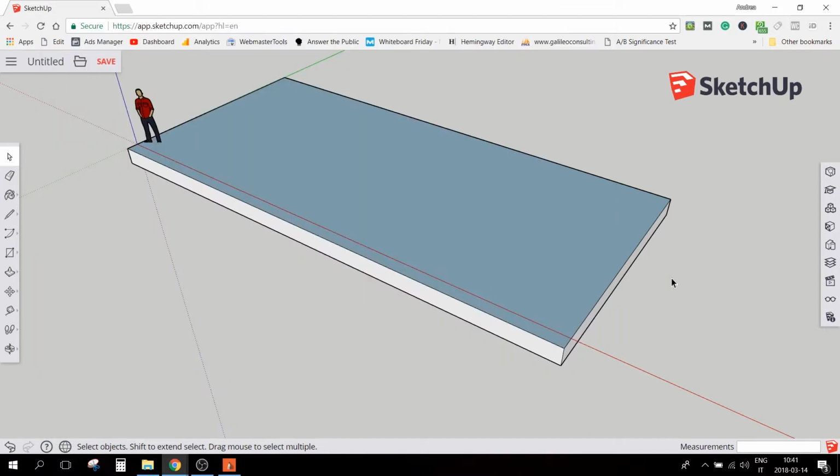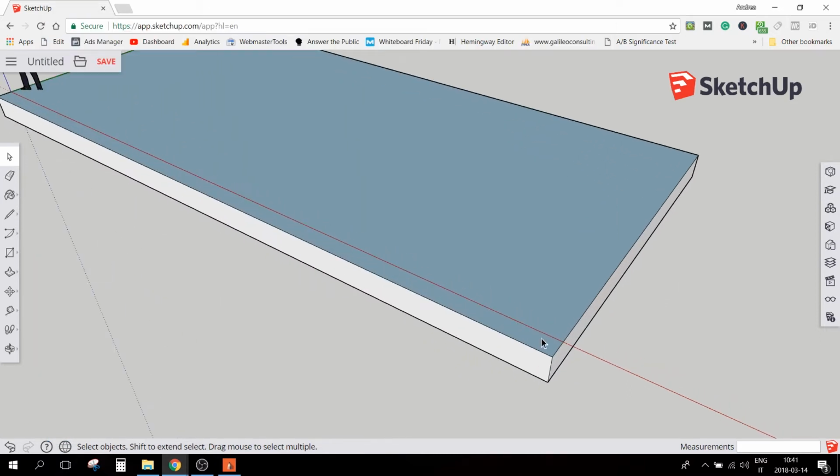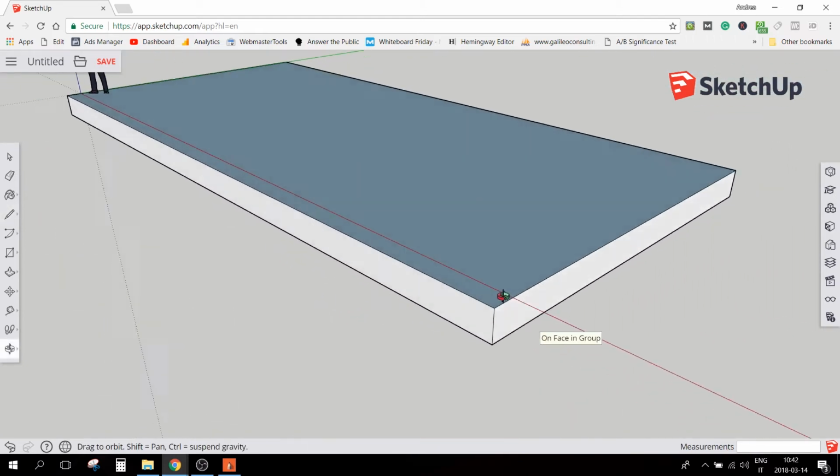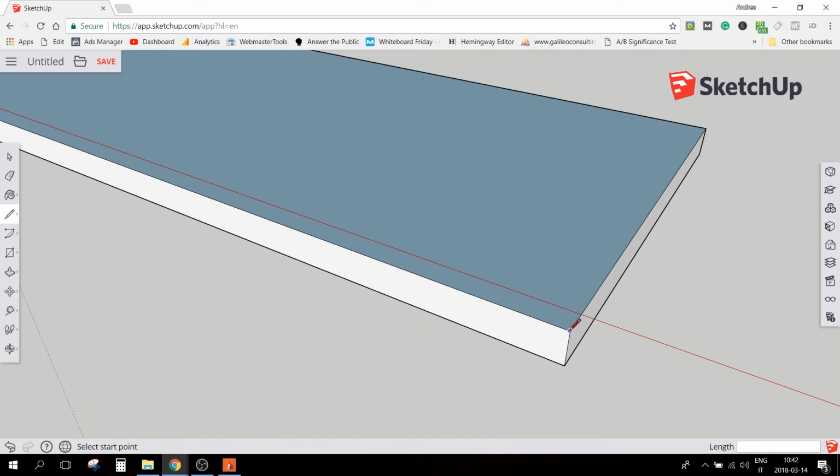Now what I want to do, I want to start building external walls, and this is very easy. So I will take a line and press L, and now note that at this moment I am not inside the object, I am outside the object. You see, I'm just on top of the object, so whatever I draw now, it doesn't stick to the object. And this is the main point of this entire thing. So 337 is the thickness of my wall, and I just draw something here, a rectangle.